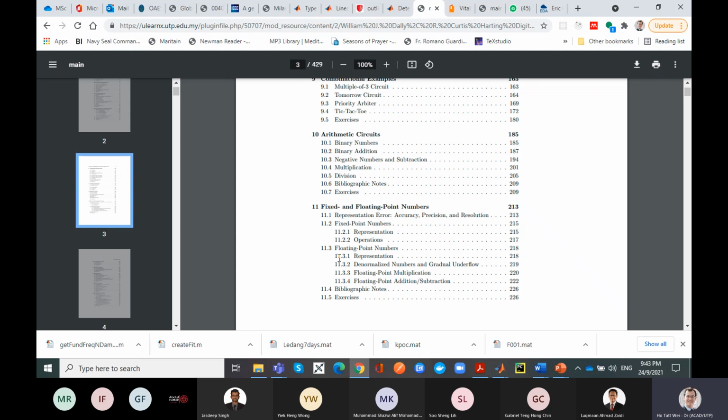So the bottleneck today is your ability to move data around. What do I mean by move data around? Well, you want to take it from memory and send it to the computation core. Whatever result comes from the computation core, you want to send it back to memory, because this is the way we do compute today. It's called the load store architecture.